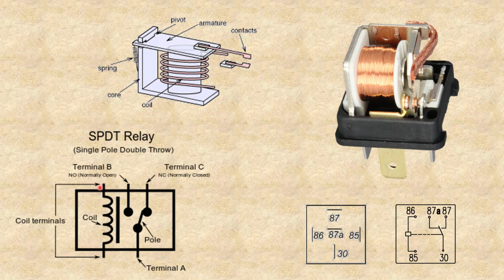Now, when this is de-energized, when there's no current going through this coil circuit, this is in a normally closed position here. It's in a normal position when it's de-energized. This is normally closed contacts. These are normally open contacts. But whenever I energize a relay, the contact states change. So upon energization, any power that was being delivered here is now diverted over to this one instead.